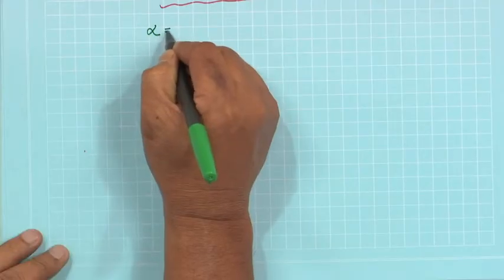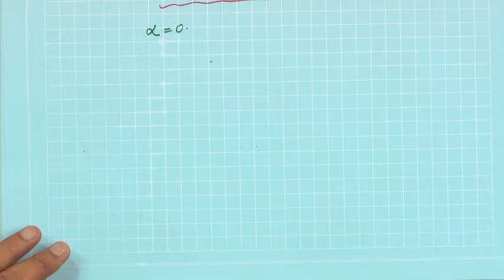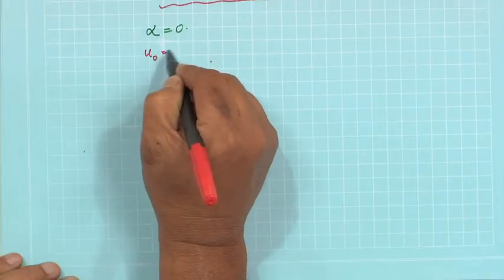Welcome to this lecture. Today we will see the broadside array. Now, what is a broadside array? When the progressive phase shift we make 0, that is the broadside array. That means no progressive phase shift between elements, so all elements are fed in phase. The moment we do this, we get u0 equal to 0.